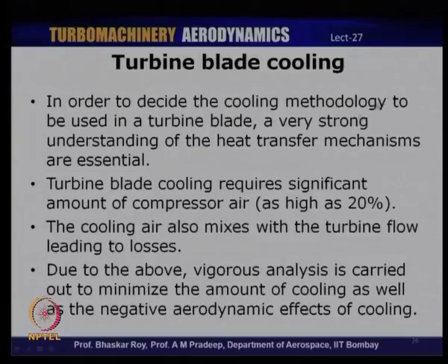Turbine blade cooling obviously requires a significant amount of compressor air, which might firstly lead to losses in the turbine, leading to lower efficiency of the turbine, and also it leads to overall loss in thrust, but that of course is compensated by the fact that you can actually get a higher turbine inlet temperature with cooling, and probably that kind of compensates. But the effect of cooling on the aerodynamic performance is something that will need greater attention and analysis to be able to achieve a cooling methodology which does not significantly affect the turbine performance.